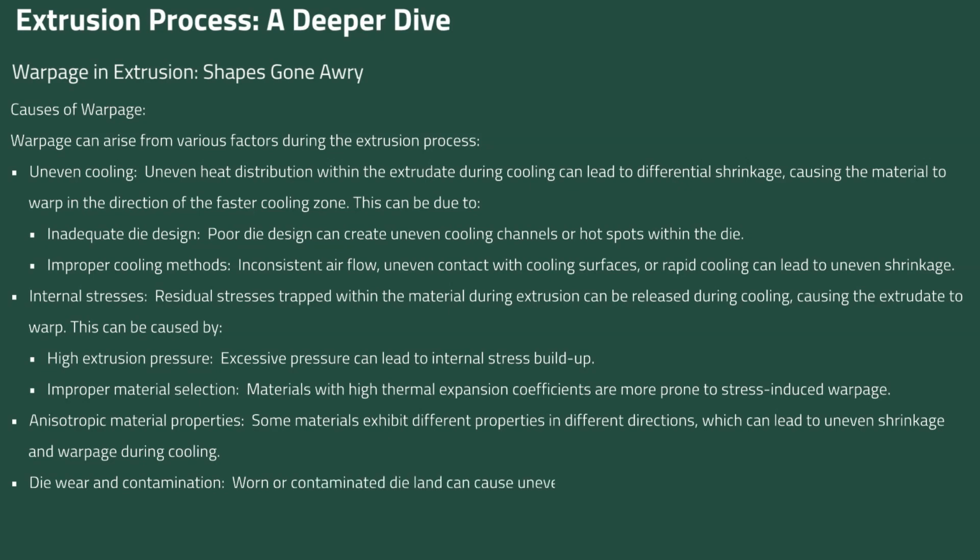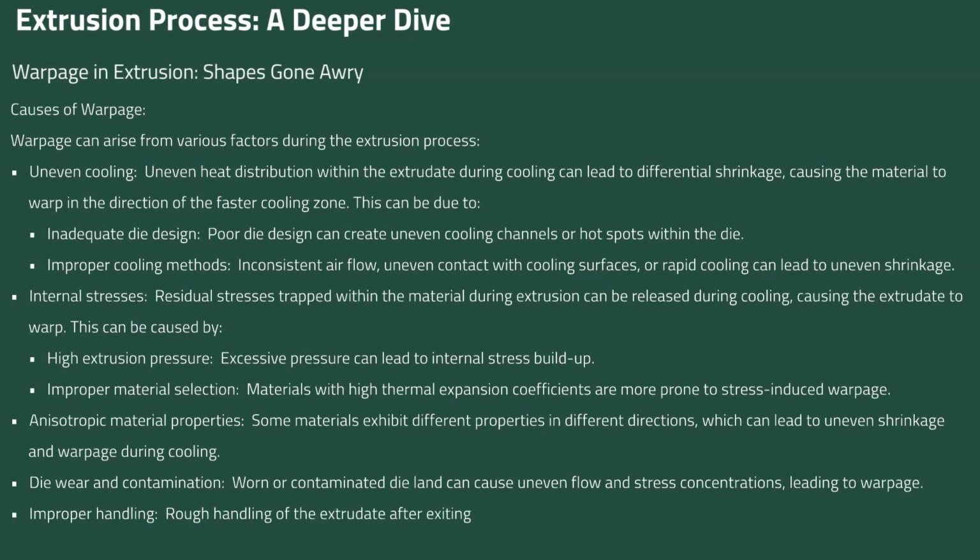Die wear and contamination: worn or contaminated die land can cause uneven flow and stress concentrations, leading to warpage. Improper handling: rough handling of the extrudate after exiting the die can induce additional stress and contribute to warpage.